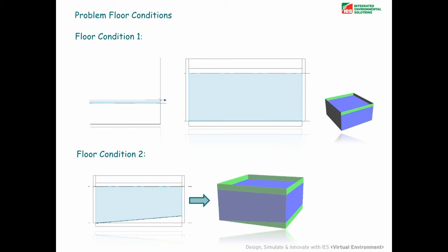So again, these are much the same things. This is just looking vertically as you go up through your building. Having multiple elements that are room bounding can cause issues. And these are generally what you would see, maybe the placed space or room sandwiched between constructions. So it's easily, again, you'll find if you select one of them and just get to your primary room bounding element, and then it will just free it up and you'll see it in front of you happening.